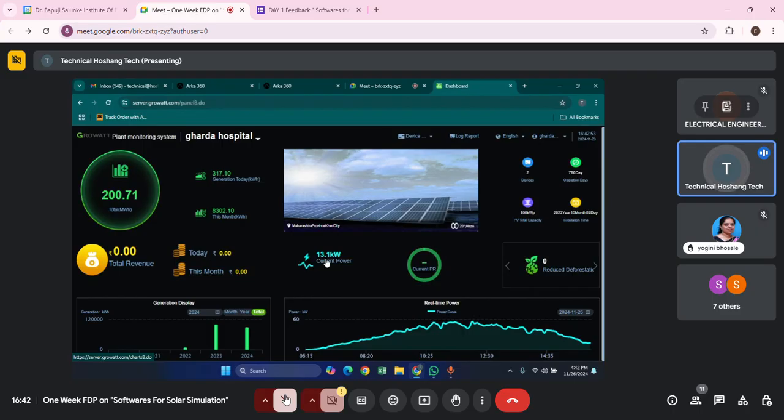And if we see the solar rooftop of our college, we are having 50 kilowatt of generation. So 50 kilowatt of generation for a 1 hour time span will be 50 units, right? These 50 units can be used for minimal purposes like street lights. As our college is daytime running, these 50 units can be very useful for keeping some lights on for night lamps, you can say. Some units can be used for hostel purposes, but in a ground-mounted structure, as soon as the time becomes 4:30, 4:35, the current power reduces.